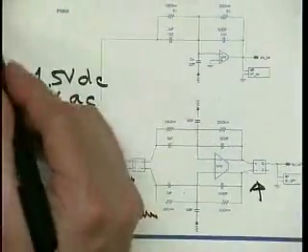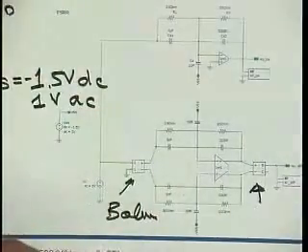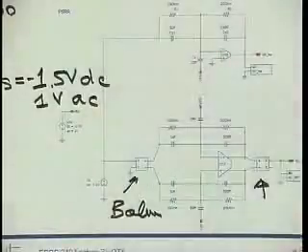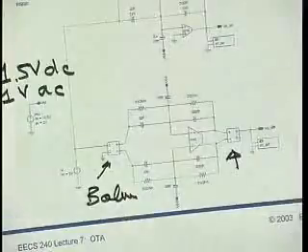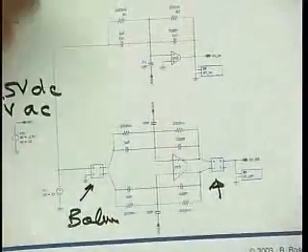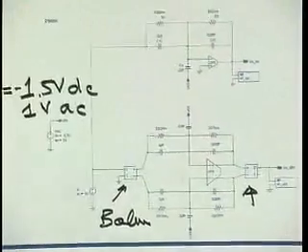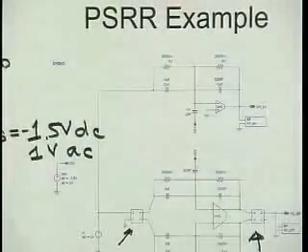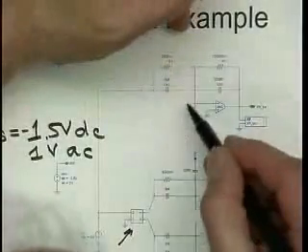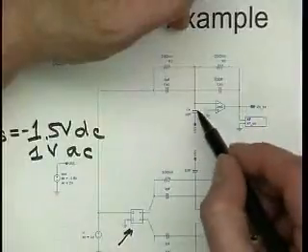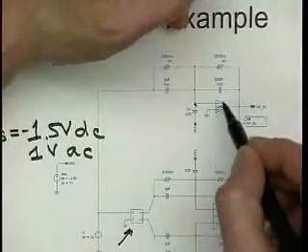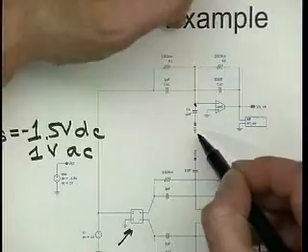And then VDD, of course, that's a DC. Well, I don't even use it here, but that would be another 1.5 volts. So plus minus 1.5 volts. It's my supply. And the VSS has this ripple on top that I model with an AC source here. Okay. Then I also put just a 10 femtofarad capacitance from the input of this amplifier to ground.